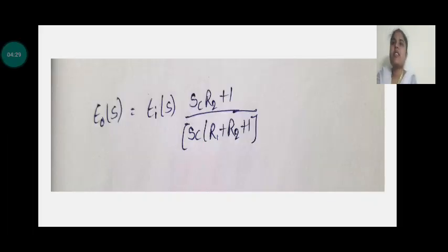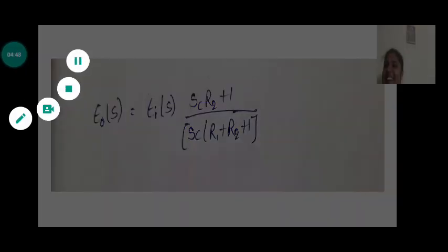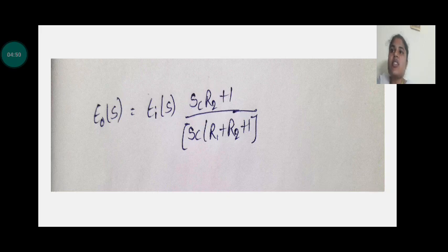In a practical system, adjustment of gain alone will not be sufficient to meet the given specifications. In many cases, increasing the gain may result in poor stability or instability. In such cases, it is necessary to introduce additional devices or components in the system to alter the behavior and to meet the desired specifications. Such a redesign or addition of a suitable device is called compensation.